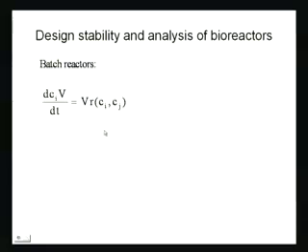It's just volume balance, and for the product, one for the concentration of the product. So this is the balance for the concentration of the product. As you can see over here, d/dt of Ci times V is V times R, R being the reaction rate, and R is a function of Ci and Cj, that is, all components.